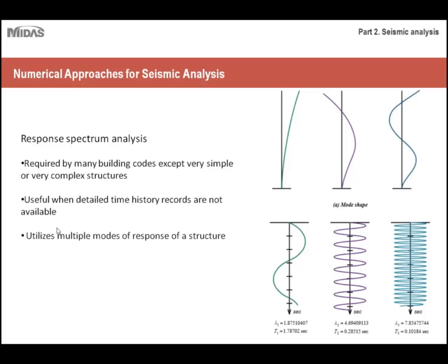Also, keep in mind, response spectrum analysis utilizes multiple modes of response of a structure. So for those of you who are new to this concept, you're probably wondering what this picture means. Essentially, with response spectrum analysis, you're saying that the structure will have several different mode shapes depending on the level of the earthquake or the level of seismic loading and the point at which it's at.